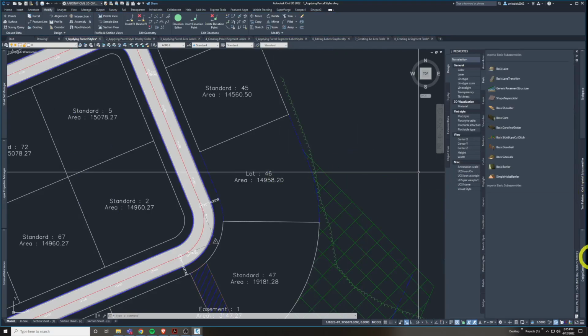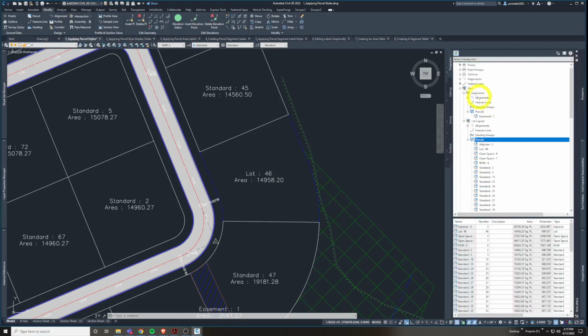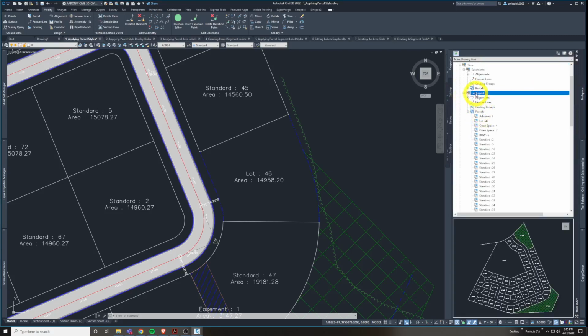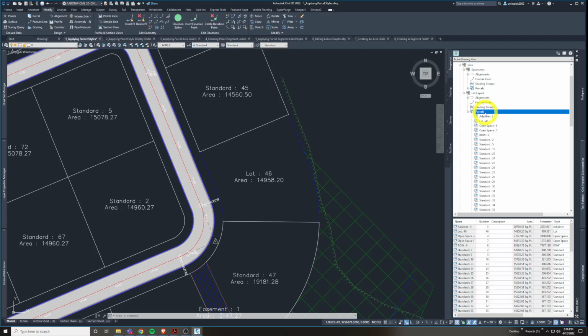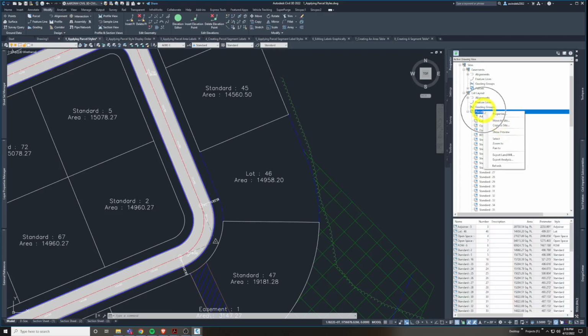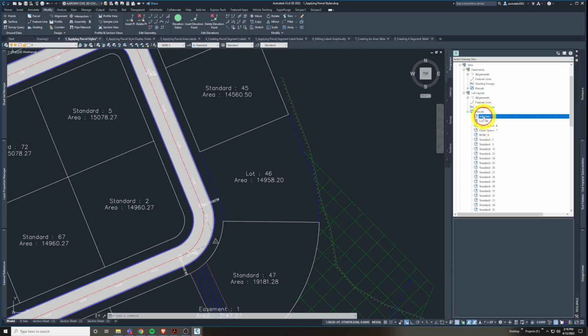On step 10, it wants us to go into the tool space, into Prospector, into Sites, into Lot Layout, which is here. Okay. Oh, also, when you have your parcels on, you have to have this selected to show the previews. So if you have this turned off, it still will be black. So you have to have both this turned on for all items and then this turned on as well on the parcel header, which is kind of weird.